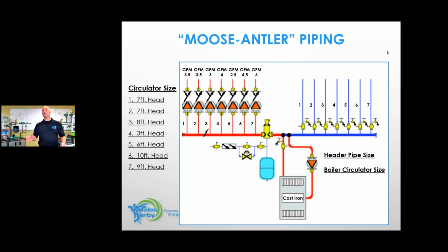I could simplify that job, put 0015 E3s on there and have them set to low or medium and meet the exact flow rates of each one of those heat circuits. Because I know no one has ever installed a 006 as a heating circulator. It's rare if you've ever installed a 005 as a heating circulator. And the cost of a 0010 for a heat circulator, it adds up.